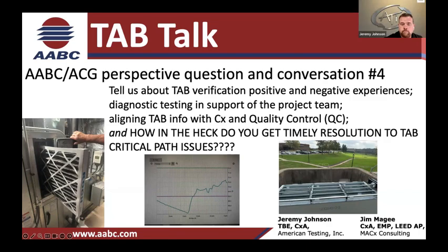Sure. Normally, a control contractor, a building operator, or an energy management guy has come in and changed the way the system operates, reduced the static pressures and that kind of stuff. So you're in trouble. The two things I can say are communicate with the commissioning guy, and communicate with the owner if you have that opportunity. If not, you can always talk to the commissioning guy and he can be the bad guy for you. For sure. Absolutely.